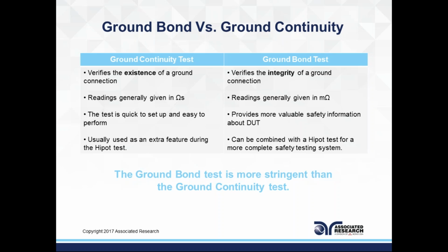We have our HiPot testers that come with a built-in continuity tester. This allows you to easily perform the most commonly performed electrical safety test, the AC HiPot test, and the second most commonly performed electrical safety test is the continuity test. So if our HiPot testers give you the capability of performing ground bond, ground continuity and HiPot test, this meets most of the standards that call out for routine continuity tests.